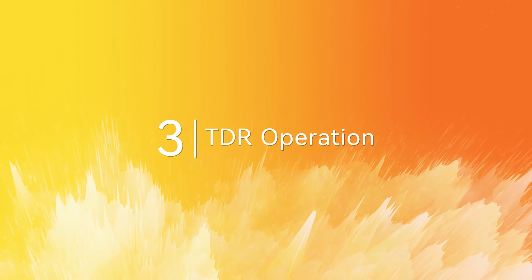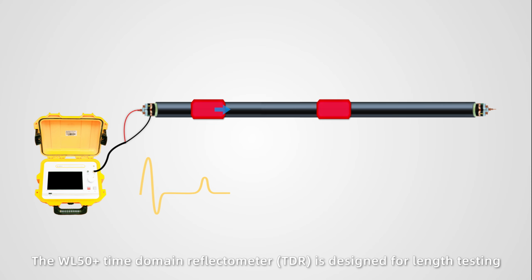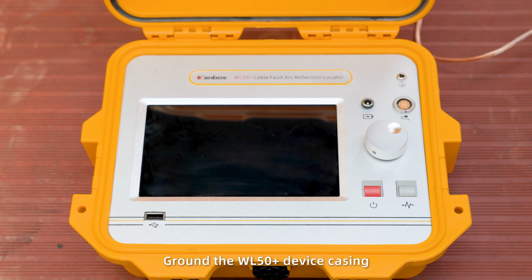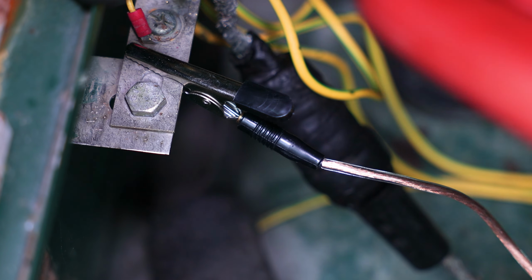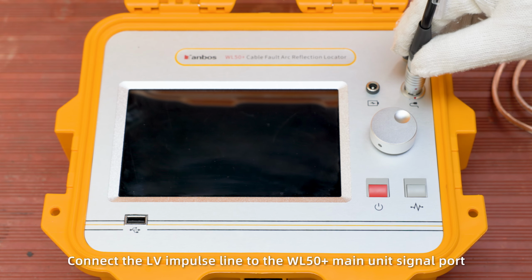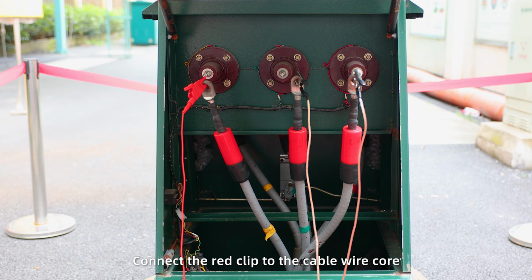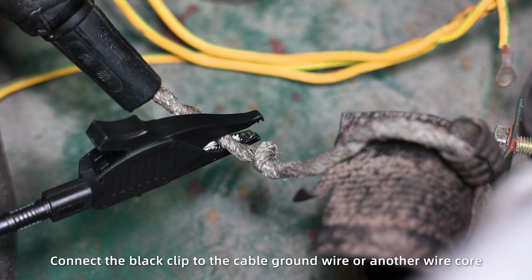3. TDR operation. The WL50 Plus time domain reflectometer, TDR, is designed for length testing and fault location on power cables. Ground the WL50 Plus device casing. Connect the LV impulse line to the WL50 Plus main unit signal port. Connect the red clip to the cable wire core. Connect the black clip to the cable ground wire or another wire core.